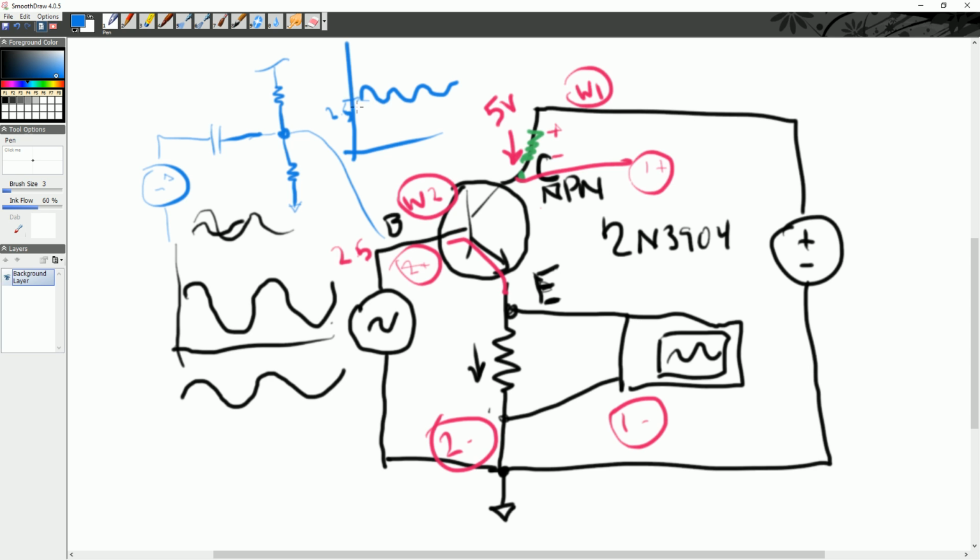And it's the DC value, right, that's going to basically determine the biasing between here and here, between base and emitter. And that's what actually turns on the base to emitter junction. It's also related to the fact that this is a 1K resistor, right? We're setting voltages instead of currents, and an NPN is a current device. However,